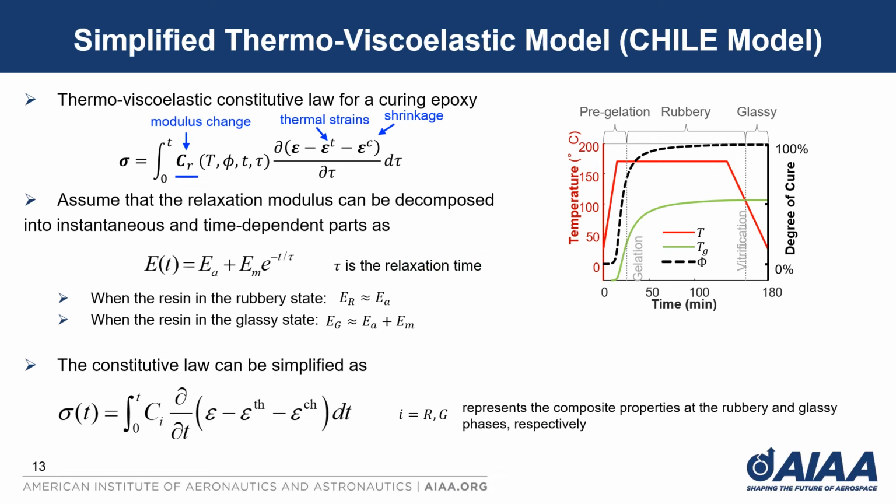For the thermoset resin, the curing process can be divided into three regions as shown. Gelation occurs at a defined point in the curing reaction, after which the resin is able to carry loads. Before this point, the resin is in the liquid phase and stress accumulation is negligible. After gelation, the resin transitions to the solid phase and the thermal and chemical strain should be considered in the